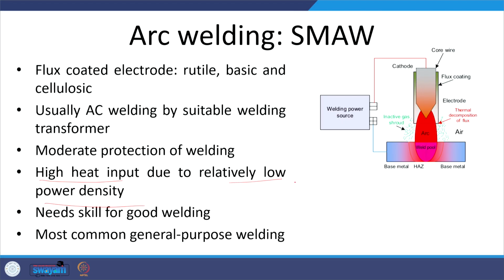Since this process is manually controlled, apart from SMAW it is also known as MMAW. How consistently and uniformly weld metal will be deposited, how good the weld bead surface is, and how sound the weld is, all depend upon the control over the heat input by control of the melting speed, and manipulation of the weld pool, or the proper placement of the molten metal where it is desired.